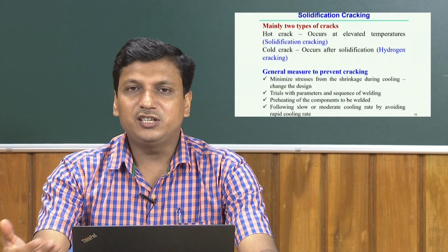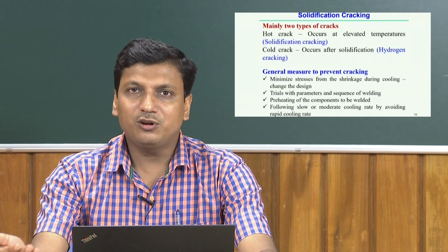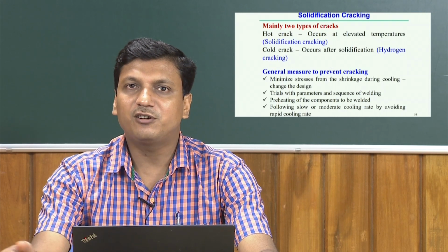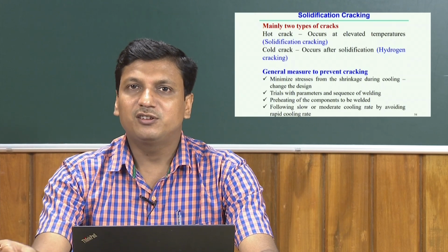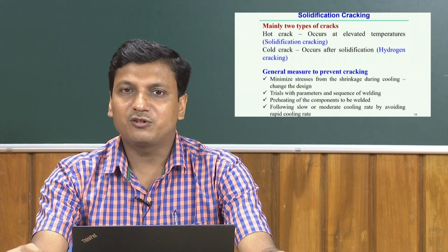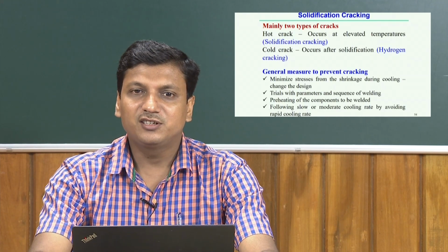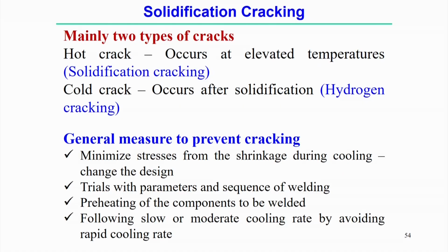So, change in design in the sense that, if it is possible, we can control the rate of cooling, maybe with the aid of some other external heat or cooling process, to control mainly the cooling rate, or to minimize the stress during the shrinkage process in solidification.